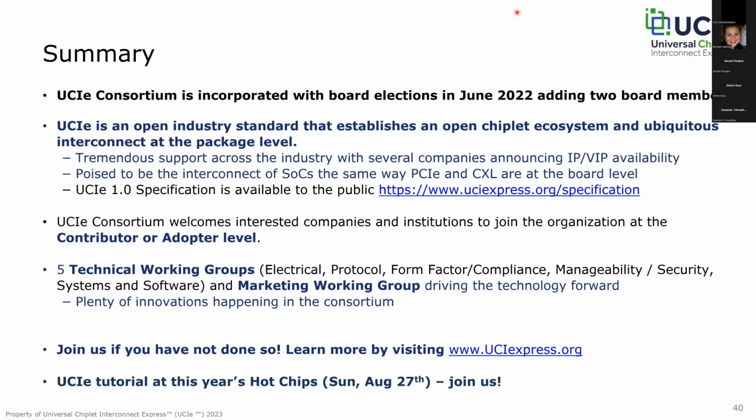whereas the standard packages give you more flexibility or longer channel reach. So trying to make the two compatible with each other would really end up degrading the performance of either one, or both of them, basically. So in order to have a separate optimization point for UCIe-S and a separate full optimization for UCIe-A, we're forced to specify them in a way where you can't interoperate them.